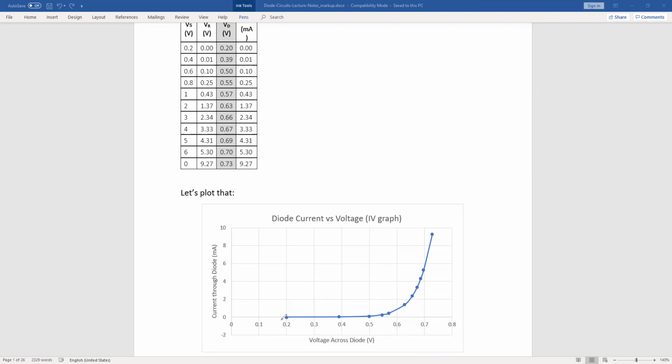That's going to start off very small because we had very small voltage applied using the voltage source. But eventually, it's going to level off at about 0.7 volts for a silicon diode. That's going to hold steady, but the current through the diode can keep increasing. That's why we have this graph that goes up once we reach that certain voltage.